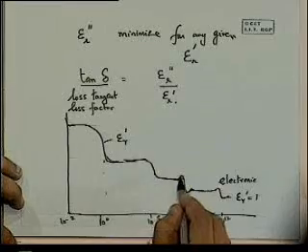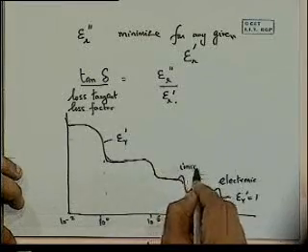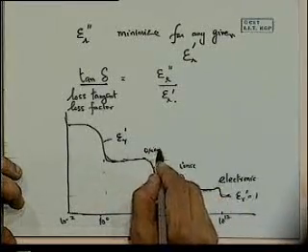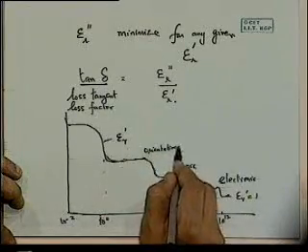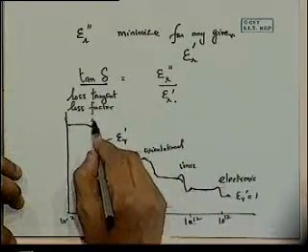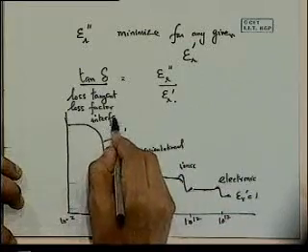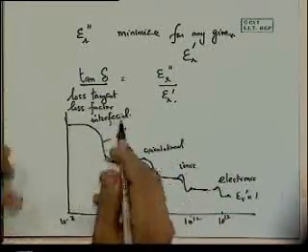What about this one? That's ionic. And then we've got orientational or dipolar. And then we have interfacial. Very good. Interfacial or space charge, because it is like charge is stored in space, much like we use the term space charge layer when we were talking of semiconductors. The same concept, that's why it's also known as space charge. So this is how the distribution looks for epsilon r dash or epsilon r prime, the real part of it.